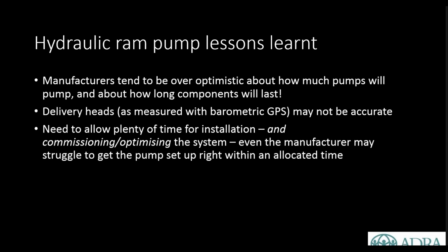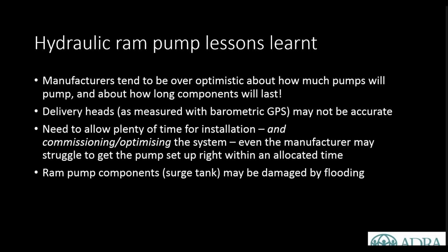One of the other lessons we've learned is that you need to allow plenty of time for installation, commissioning and optimising the system. The day that the pump actually gets running for the first time isn't the day your work is over. There's still optimising, troubleshooting and commissioning glitches that need to be ironed out before the person installing it can consider their job done. In our case, even the manufacturer who came to install it took longer than he thought to set the pump up within the time he originally gave us.